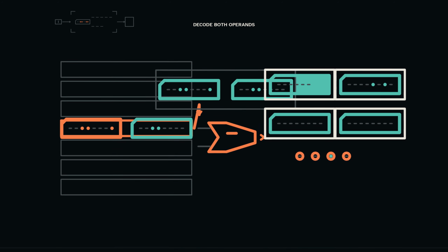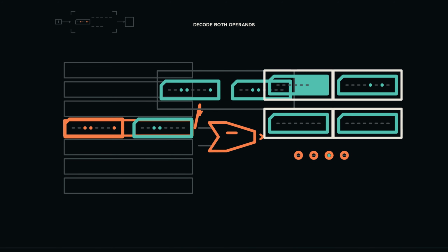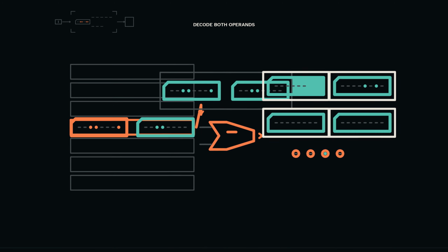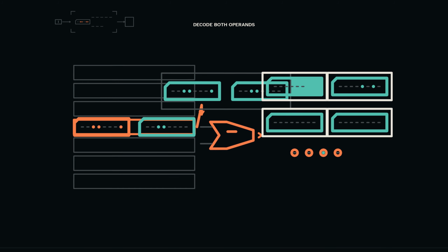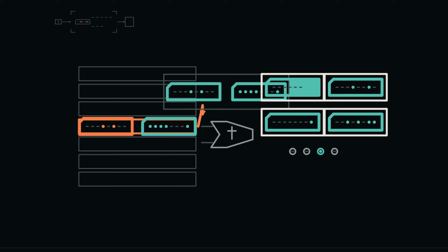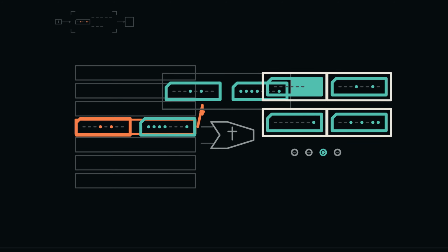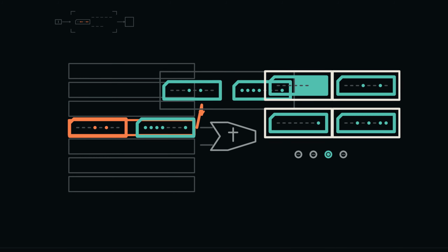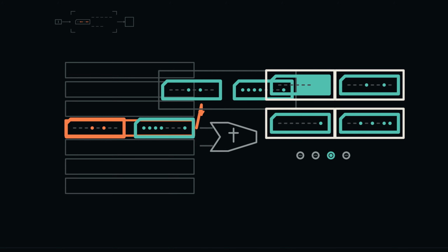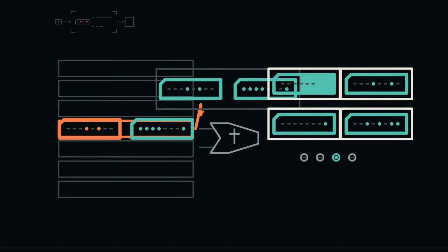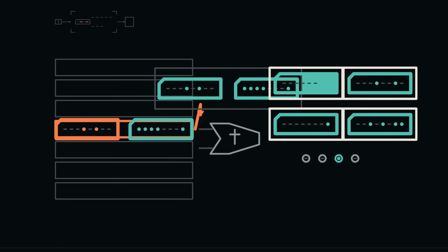The change of meaning did not happen inside the wire or the key. It happened because a specified arithmetic operation transformed one stored pattern into another for a receiver that will use the result as a quantity. The program now enters a second polling loop. This loop waits for the plus key press, not for a combined expression. At cycle 95, a new physical event has produced a new report, and the adapter queues hexadecimal 2b. Status changes independently for this arrival.